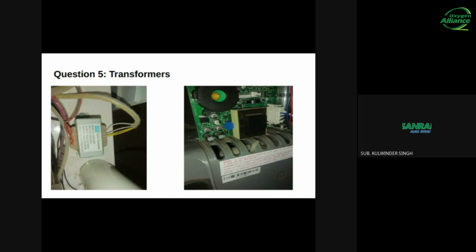Another important factor is the impedance of the transformer, which affects the stability of the electrical system and the voltage regulation of the transformer. Different transformers can have different impedances, and using a transformer with a different impedance can result in unstable operation and poor voltage regulation. Finally, transformers can have different mounting arrangements, connections, and terminal configurations also. So these physical differences can make it difficult to simply replace one transformer with another.